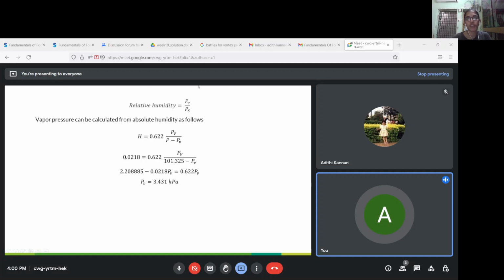So now we have your vapor pressure. We need to find out the saturation vapor pressure. The equation for that is given in the question. Pw naught is the same as PS that we have been dealing with in our lecture videos. Ln of Pw naught is equal to 18.6556 minus 5217.635 divided by T plus 273, where T is substituted in degrees Celsius.